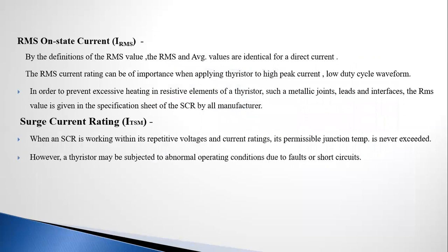Now RMS on-state current. By the definition of RMS value, the RMS and average values are identical for direct current, and the RMS current rating can be of importance when applying a thyristor to high peak current, low duty cycle waveforms. In order to prevent excessive heating in the resistive elements of the thyristor, such as metallic joints, leads and interfaces, the RMS value is given in the specification sheet of the SCR by all manufacturers.